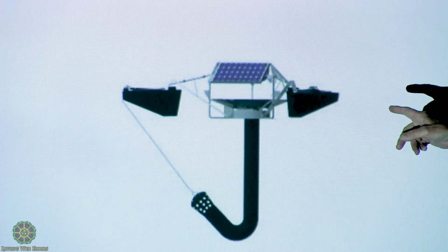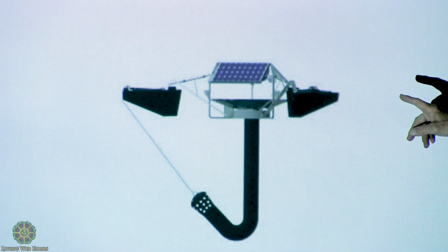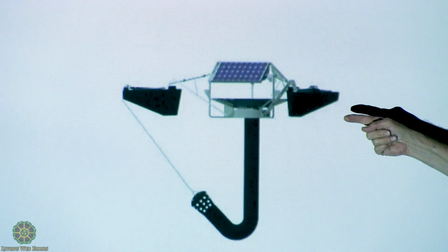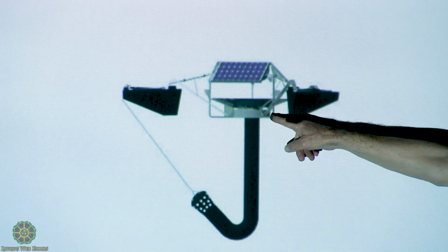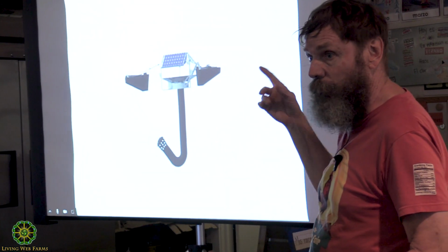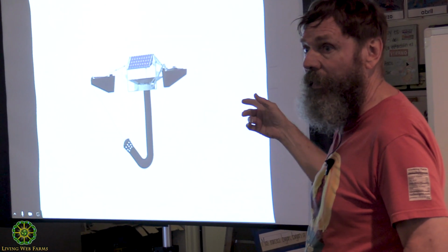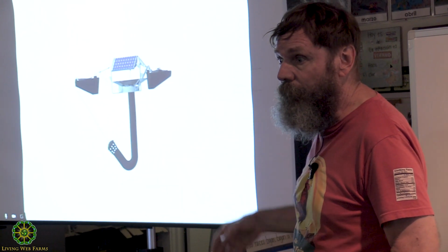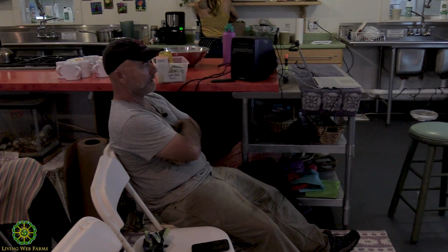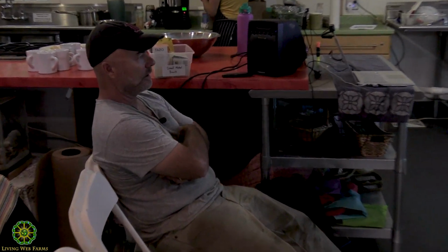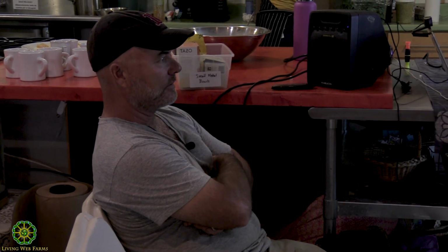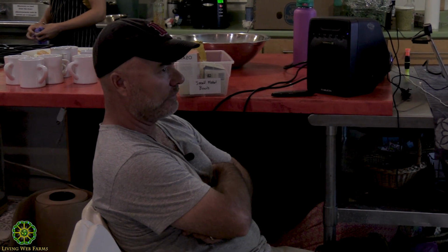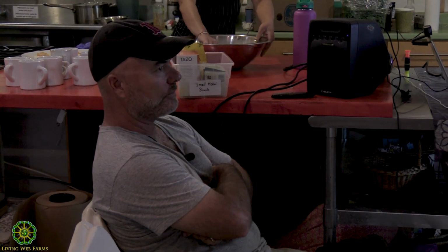And on the top are two solar panels on an A-frame, and a battery is installed somewhere in here so that at night the stored energy from the daytime sunlight is utilized. One of the most critical times to aerate a pond is between around midnight and dawn. That's when the dissolved oxygen is lowest. So that's why direct solar doesn't always work as successfully, because that's when all the algae cells are dying off and taking all the oxygen out of the water, and that's when you'll get a fish kill.